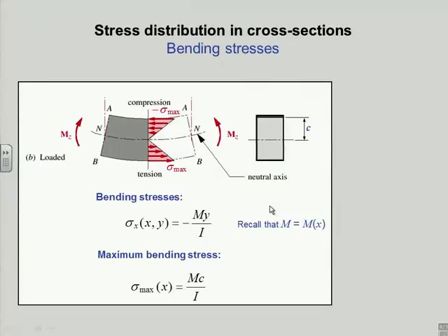Okay, so this depicts the stress state across the cross-section of a beam in bending. As we just observed, the top half is in compression, the bottom half is in tension. And the thing labeled N is called the neutral axis. And that's called neutral because nothing's happening on it. That's the transition between the compression and the tension, right? So there's no bending stress, it's zero, on the neutral axis.